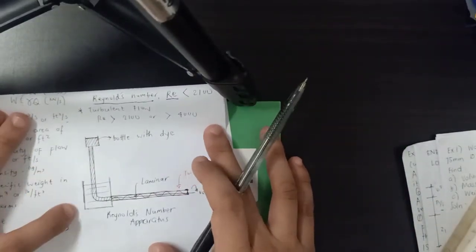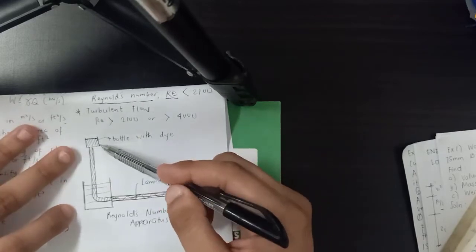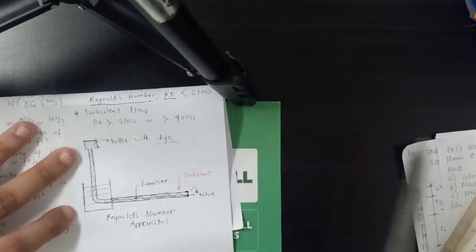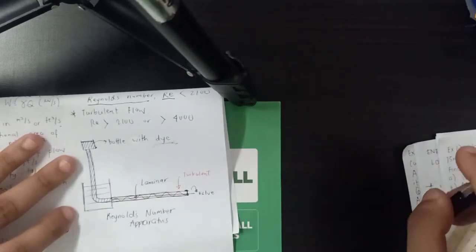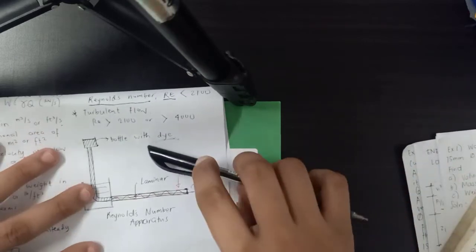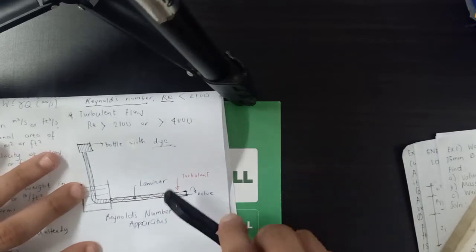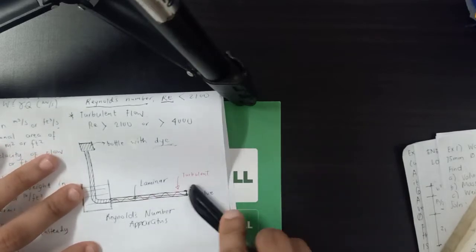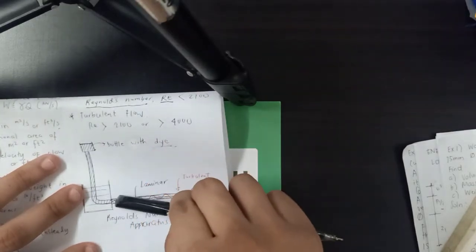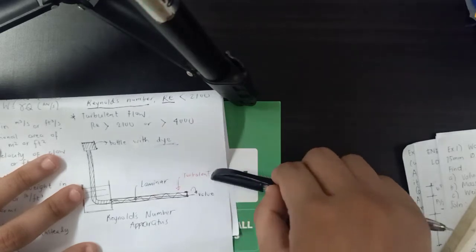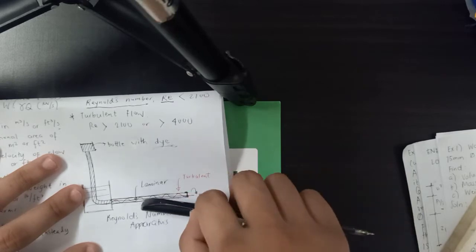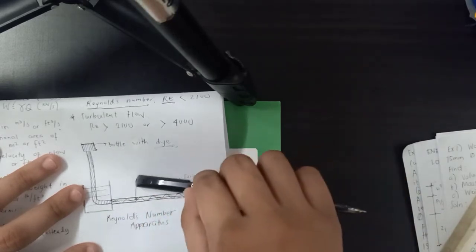As you can see, there is a bottle elevated, a bottle with dye, where you put dye using floor wax or anything colored. In this Reynolds number apparatus experiment, they can see the color in turbulent flow. Turbulent means irregular movement, continuously crossing each other, while in laminar flow, the flow is continuous.